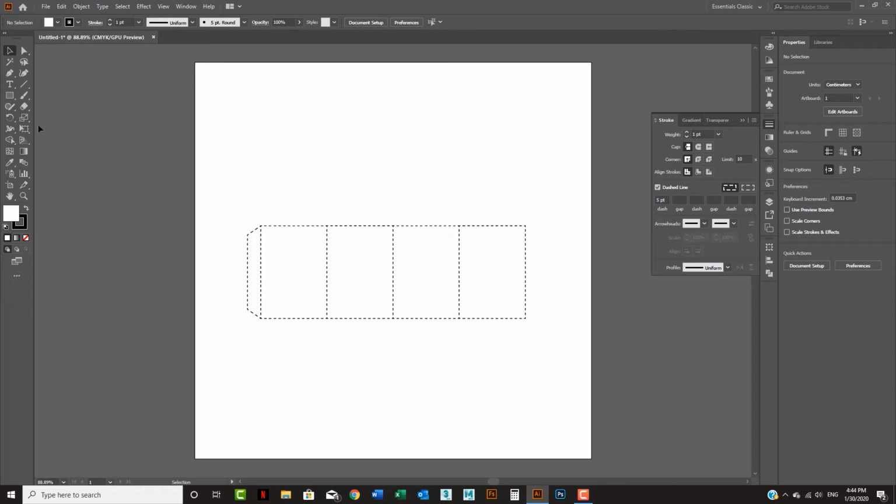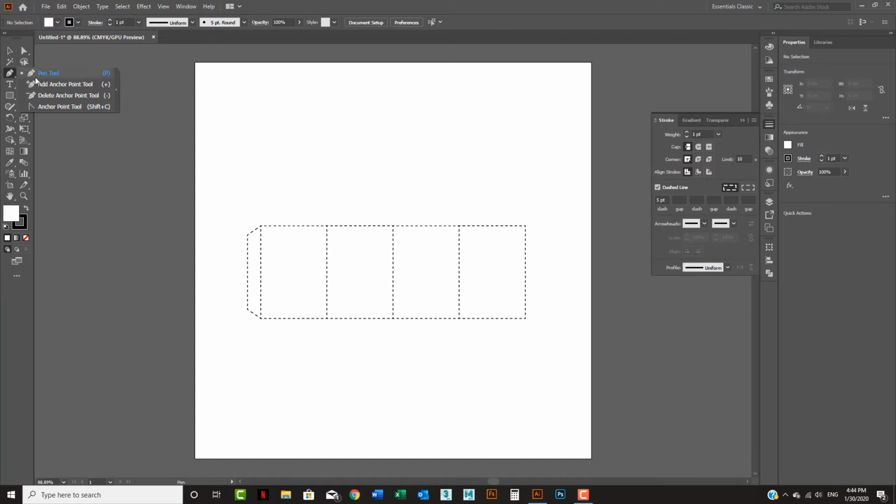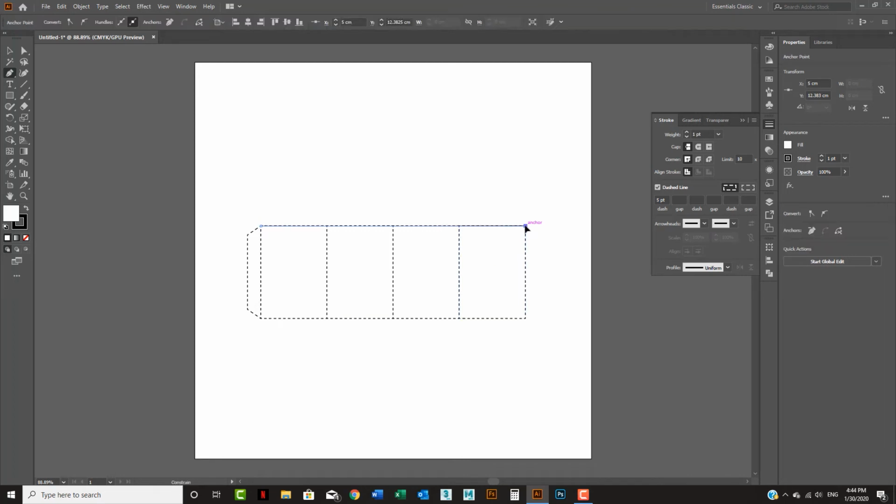For those things, I'm going back to the pen tool here, or you can use the line segment tool here, but I'm going to use the pen tool. Then I'm going to do one click here, hold Shift because you need the straight line, one click in here, one in here. Because your snap is active, you can easily snap to the already existing point. You cannot see anything, and there is a reason: because you have a fill color in.